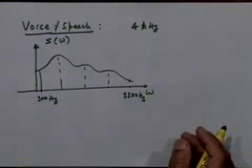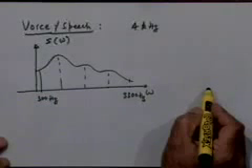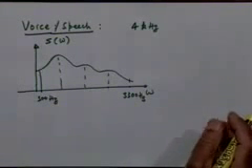But I must mention, this is not the actual bandwidth of the speech signal, right. The actual energy plot extends beyond this and goes on up to about 7-8 kilohertz. And if you want really good quality, studio quality speech to be heard, you must process that entire band properly, right. But these are the standard values that we take in telephone communication. It's found to be adequate, right. Now before I leave this signal, I'd just like to say a little bit more about it, right.